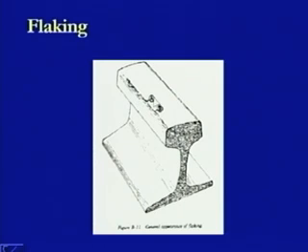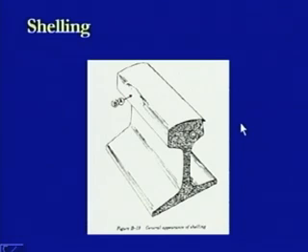Again, these things can be categorized based on the location, based on the type of the wear, as A, B or likewise. Then another condition which can get induced is shelling. Shelling is a higher category of wear as compared to flakes, where the flakes were coming from this section in the longitudinal direction like this, whereas in the case of shelling it is the removal of the mass from a certain location.